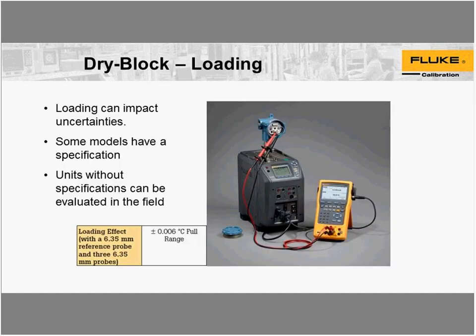Another consideration is loading. It can impact uncertainties because, depending upon the well design itself, I've seen some folks take a fairly small well and then try to calibrate a fairly large sensor. Sometimes the sensor size is just more than the well is designed to handle.